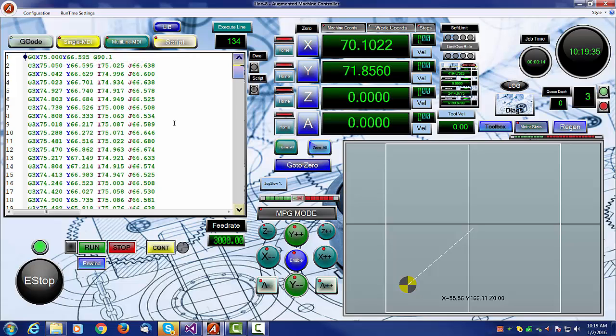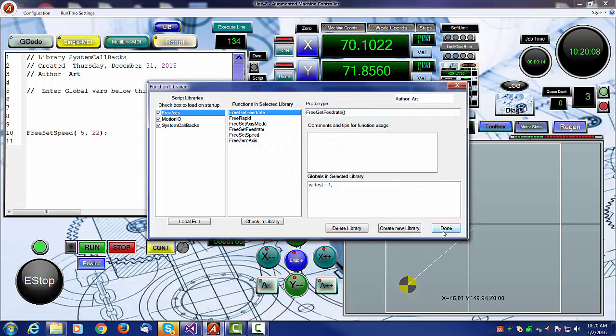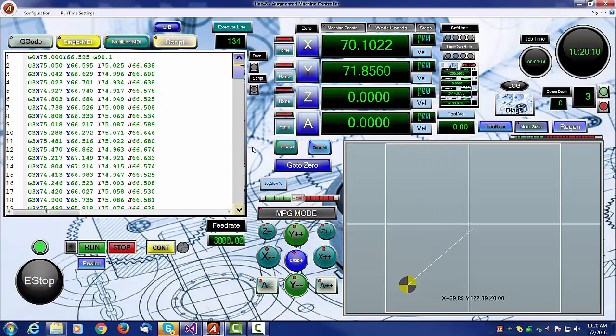Parallel scripts are also being introduced where you can specify that a script runs in linear time, like a G-code command does, or that it runs in parallel. So once the script starts, the G-code continues, and so too does the script. So you could have multiple parallel scripts stacked up, each monitoring a part of your system, one adjusting the spindle based on the temperature of the spindle, or one adjusting laser power based on an infrared camera's output, whatever. So these are some of the changes that have occurred. You'll see the library appear with its new library readings soon. I'm just working out a final few bugs before I make a release.